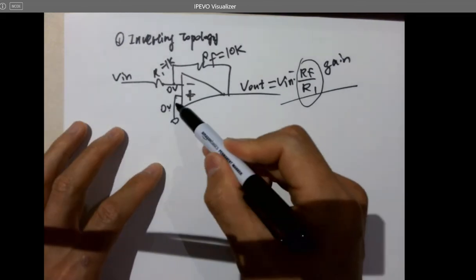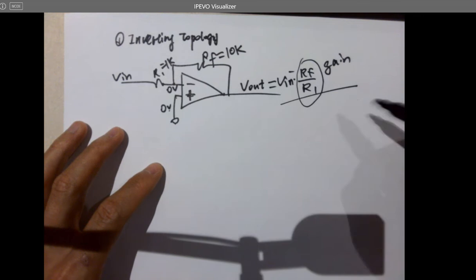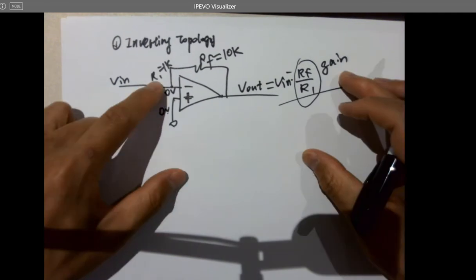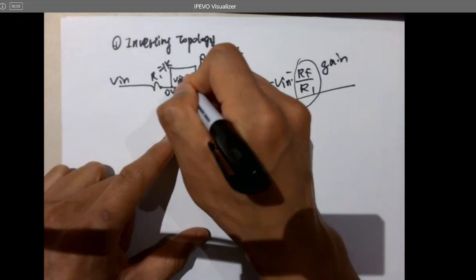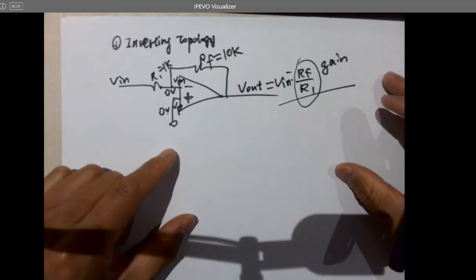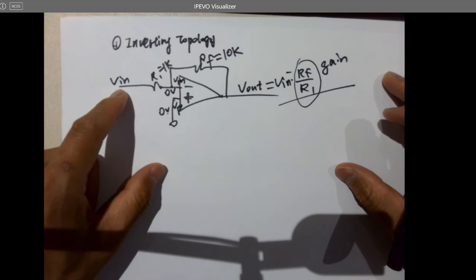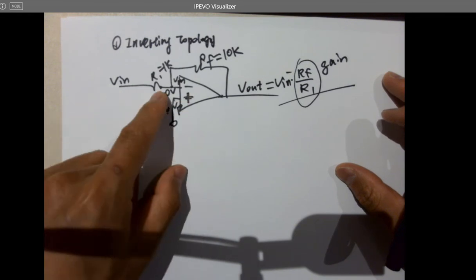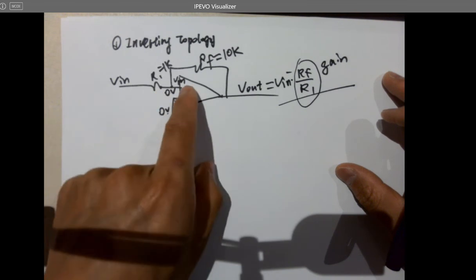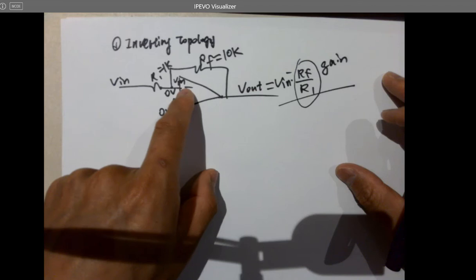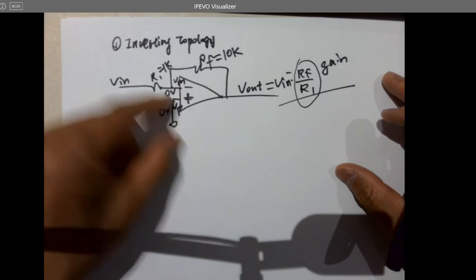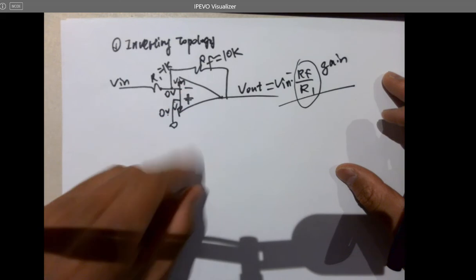So these two are equal. How to understand that? So first, one interview question. So VP equals VM. So that's VM, that's VP. Keep in mind, this is VIN, this is not VM. They have different voltages because of the resistor. Is that reasonable? They're not the same node. So VM, VP are always a wire directly shorted to the terminal, not something else, right? So this is VM, this is VP, always labeled very close to the terminals.